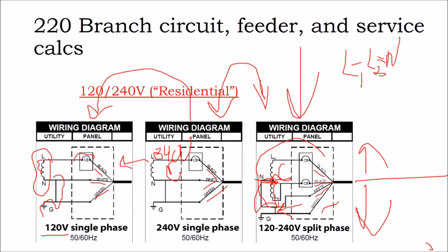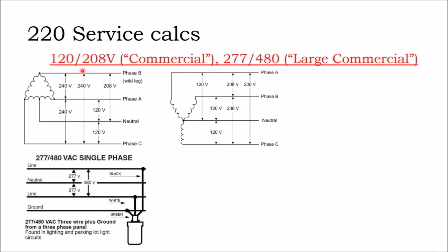That means that the neutral is not just sitting there connected to ground at 0 voltage. That means that there are many times that the neutral line is carrying current in your home. In fact, it's designed to carry current. In fact, in a solar array, that neutral must be sized to be the same size as your electric load, as a continuous load, but not on all homes do you have that same continuous load, and so they might undersize the neutral.